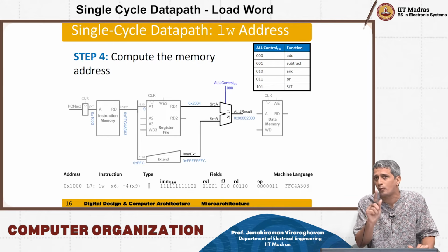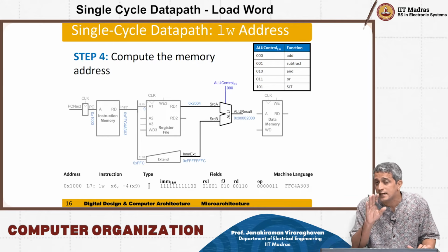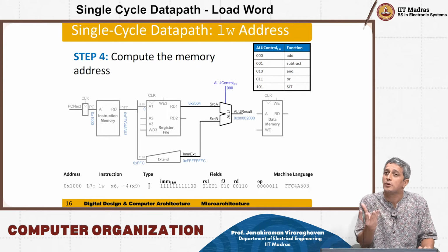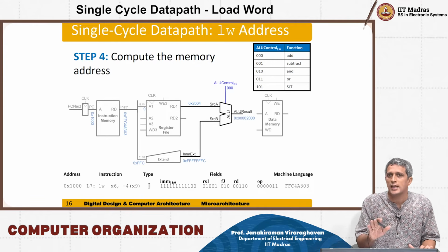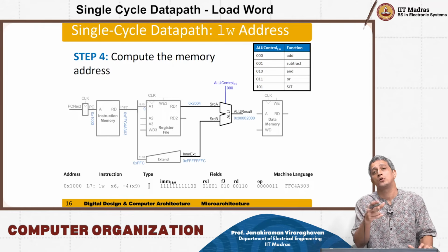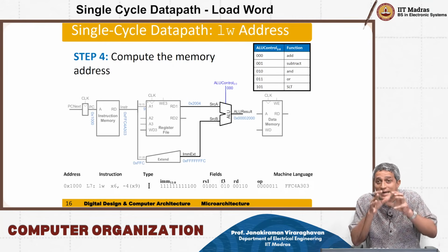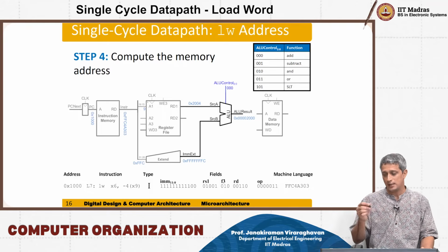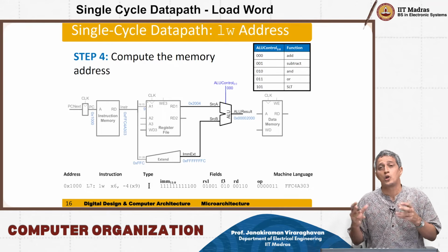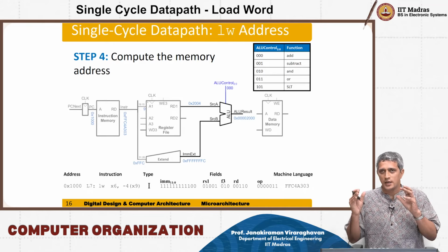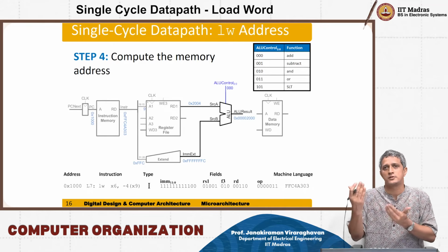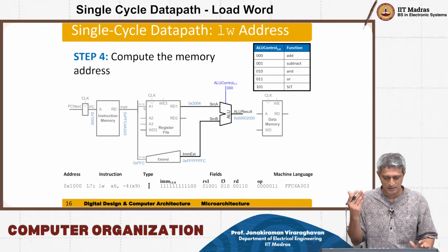There is no ALU operation being done on the data that is being fetched from the memory directly, and therefore the ALU can be reused here for address calculation, without worrying about having to do some computation on that data. So that's why this RISC-V type of architecture is also called a load store architecture. And if you did not do this, you would need another ALU to actually do this data manipulation separately.